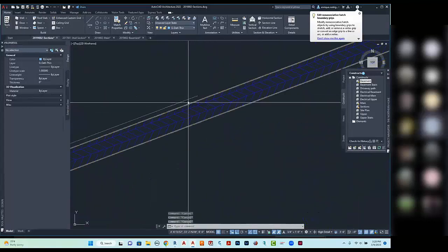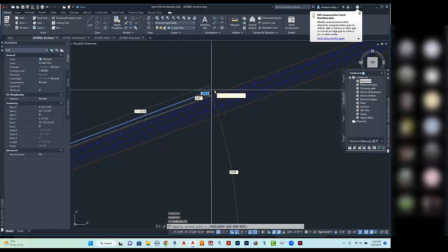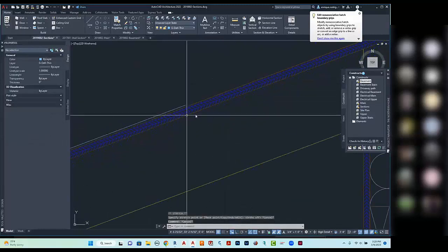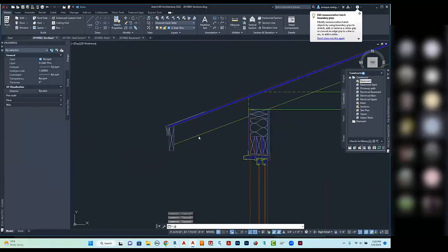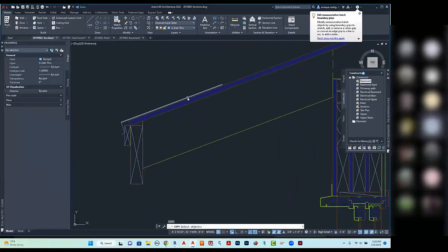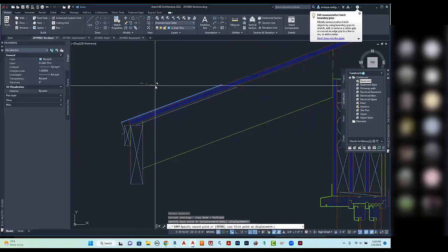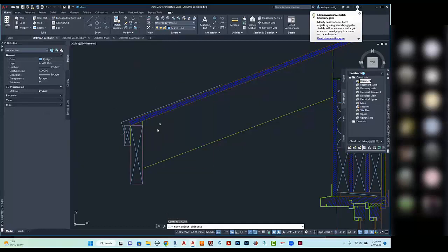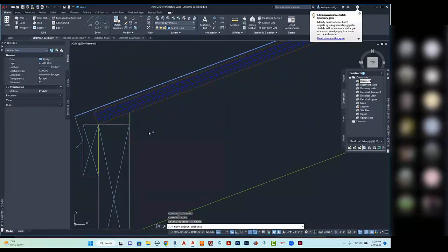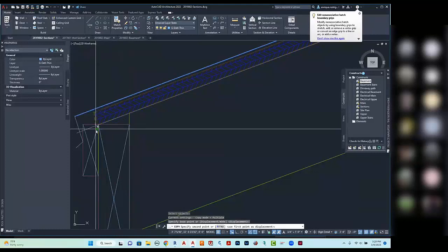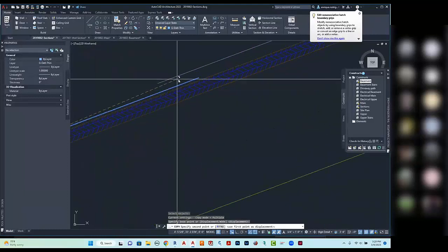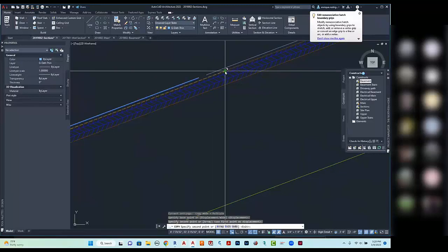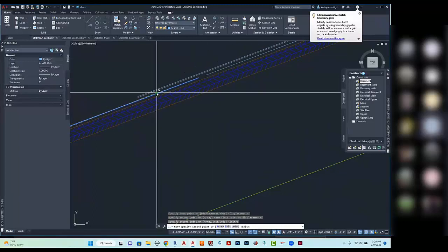So let's go ahead and extend this guy, the ortho off. Let's go ahead and copy this guy. We use the proper angles. Repeat copy. I'm going to copy it from here, so I keep the same angle. And I'm going to copy it to somewhere up in here.